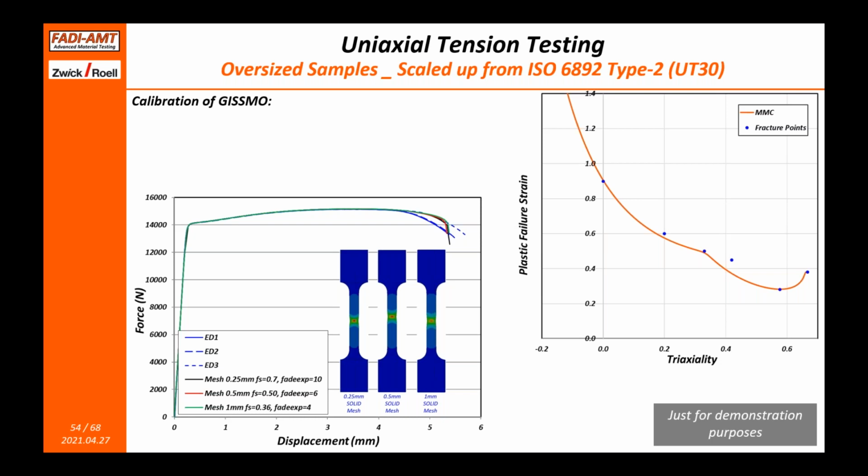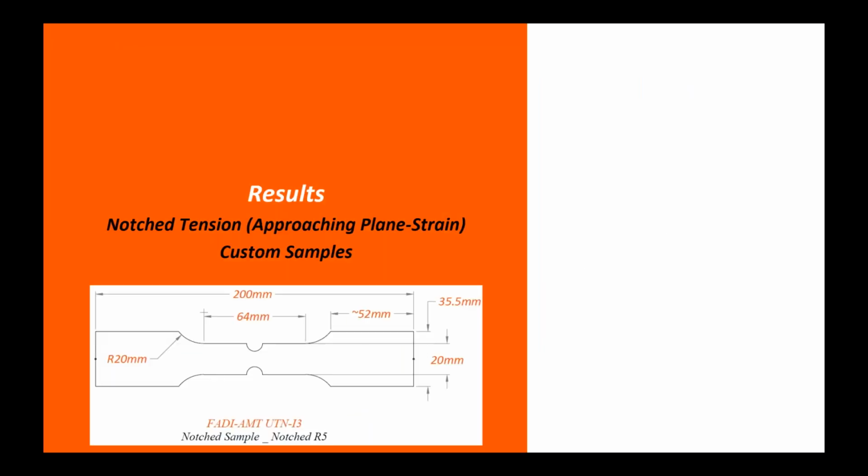So in short, even if you want to use your 2D DIC for obtaining fracture strains, you should still be able to get very good results, without affecting the accuracy of your outcome, basically, in terms of feeding it into a fracture model card. Let's go to other examples of tests now.